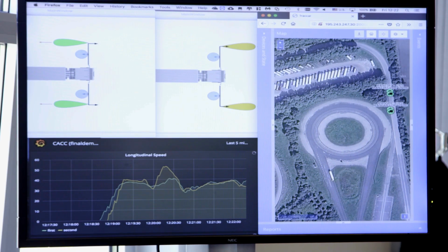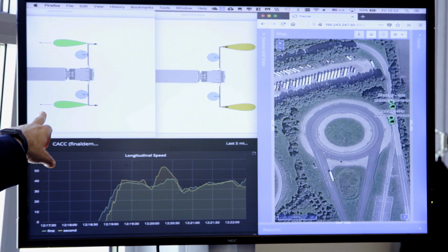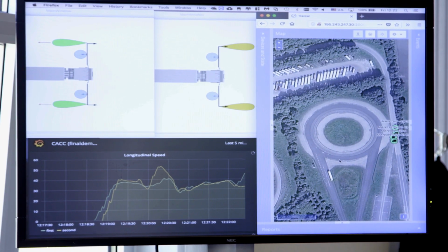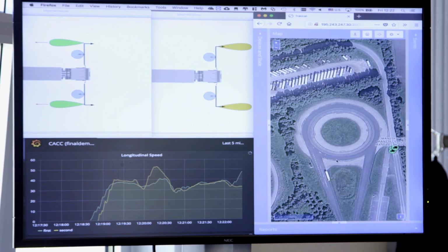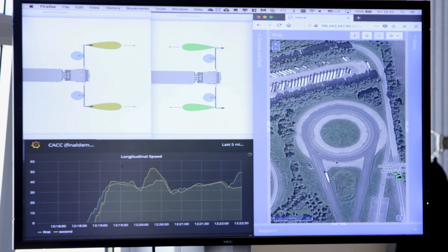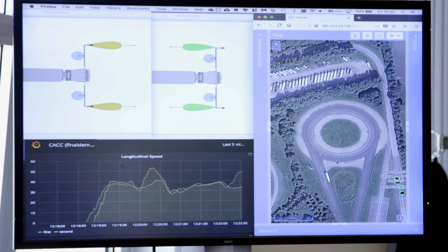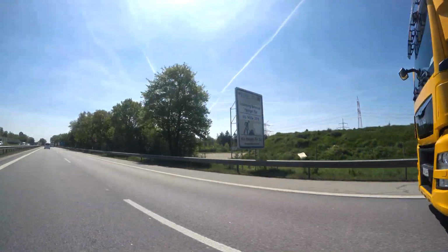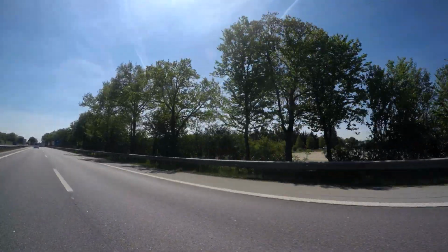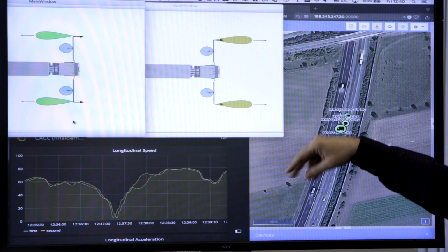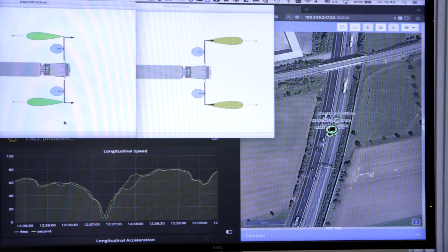The specific mode can easily be demonstrated in an overtake scenario. In this example, an overtaking maneuver is taking place inside the MN test track. It can be seen that as the following vehicle overtakes the preceding vehicle, the patterns gradually change from looking front to looking right and then to looking back, tracking the cooperating vehicle. A corresponding pattern reconfiguration takes place in the other vehicle.